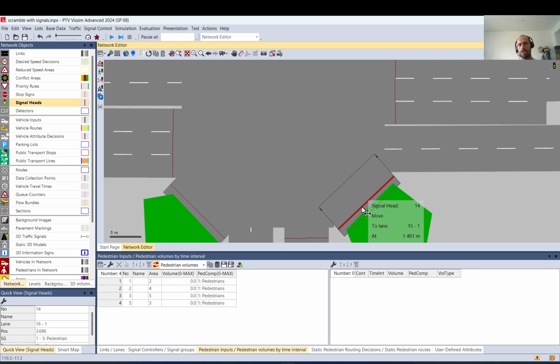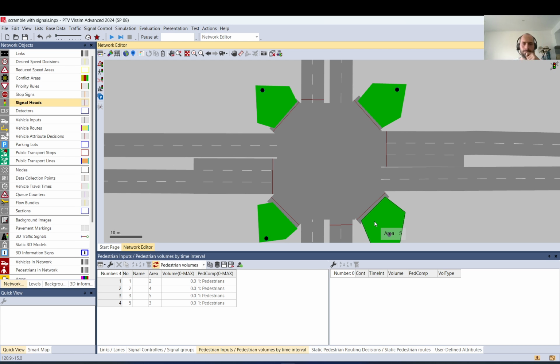Tab, change it. This is very important because if it is like this, pedestrians can just walk across when they go into the intersection, but they cannot get to your area when they leave it. So that's the trick. That's what will help your pedestrians to complete their movements in intergreen or during the intergreen. Okay.